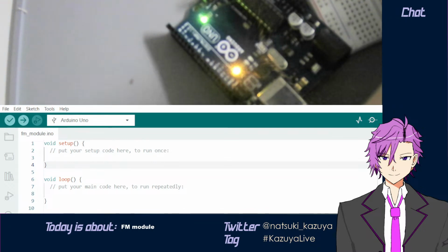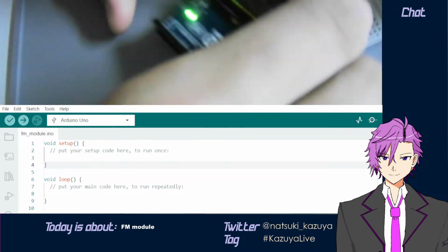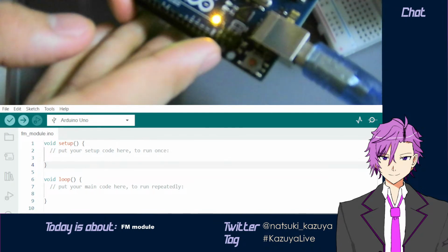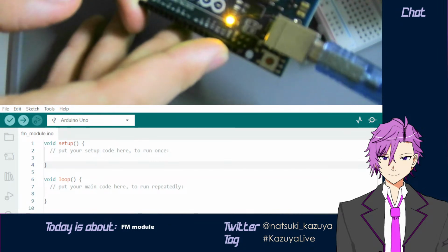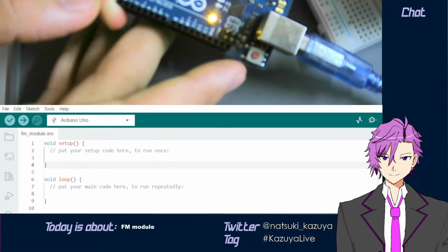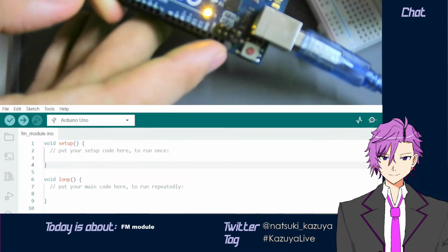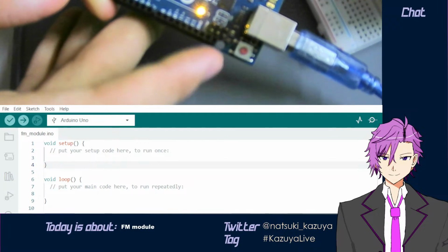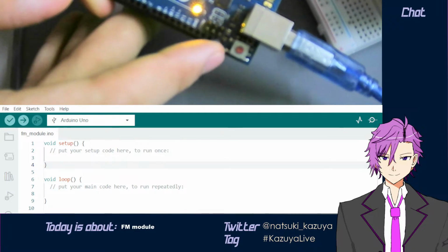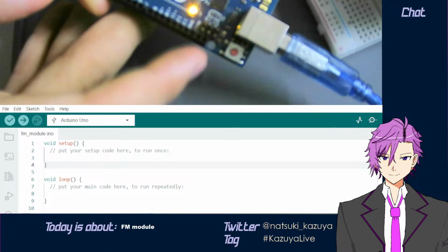Okay. So the full Arduino Uno guide, circuito.io. So okay, there we go, found it. So I think if you see this very carefully, the furthest pin is actually SCL, and the pin before it, we'll call this a female pin. So the female pin, the furthest one is SCL, and the one next to it is SDA.